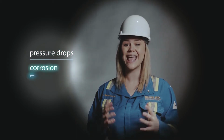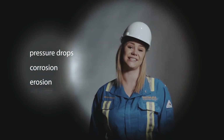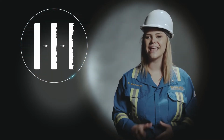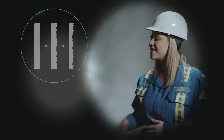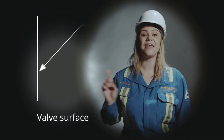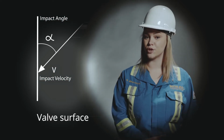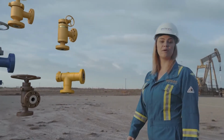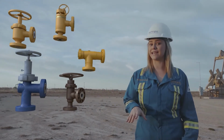Choke valves are continuously subjected to pressure drops, corrosion, and erosion, which can cause expensive breakdowns. Erosion is the process of material destruction. A well stream typically consists of a mix between oil, gas, water, sand, and other various particles. When all of these elements hit the internal surface of the choke valve, it can cause erosion. The material properties of the choke valve and the impact velocity and the angle of the fluid particles affect the rate of erosion. Let's discuss how erosion affects several choke valves currently in use.